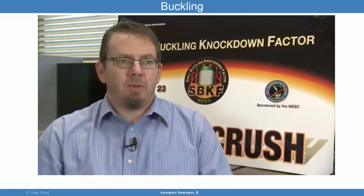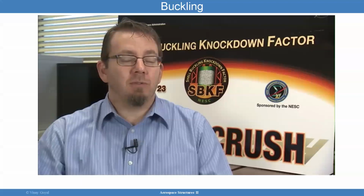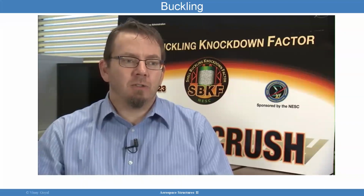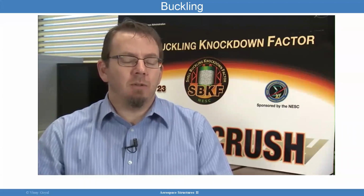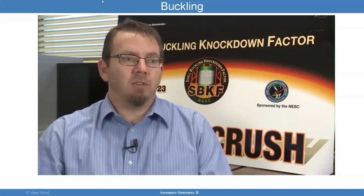In this test, we're going to be trying to simulate a lot of the same types of loads that a launch vehicle would be subjected to during flight. That includes internal pressure associated with the fuel tanks, as well as flight loads that you would see, and that would include compression type forces and bending forces, similar to what would happen if you crushed a beverage can under your foot.